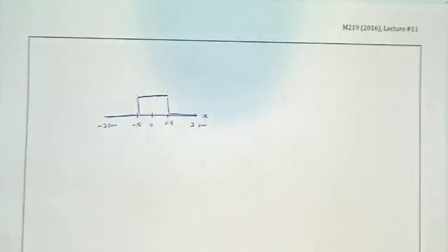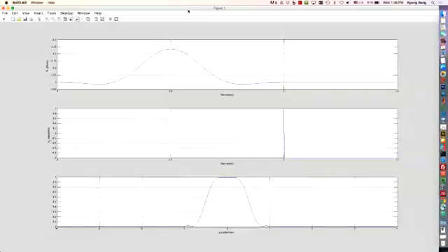But because you're using only time bandwidth product 4, this is what you get. So typically, I think this is the 0.5 point. There is some signal coming out beyond 0.5, and even in the area less than 0.5, it's not perfectly excited, but it's somewhat close to the rectangular shape. Okay?